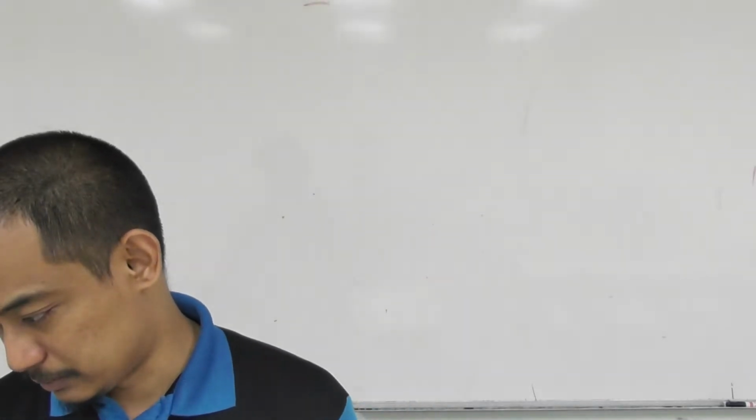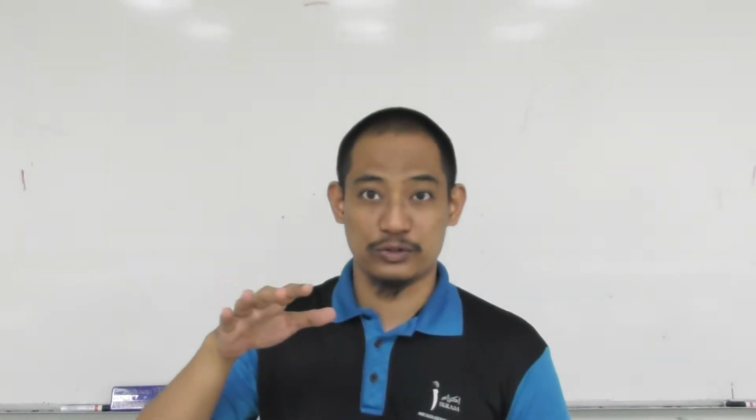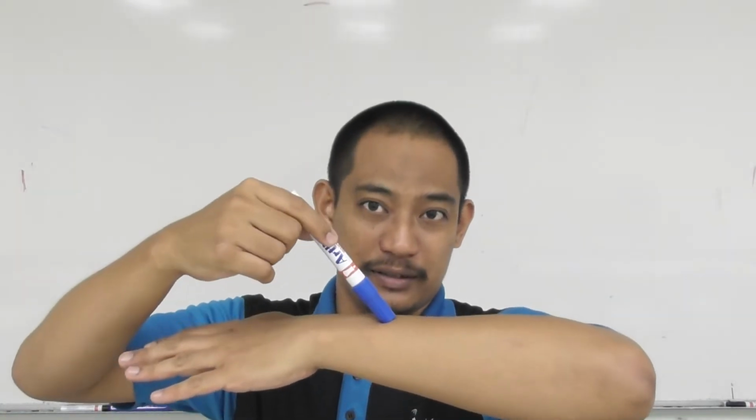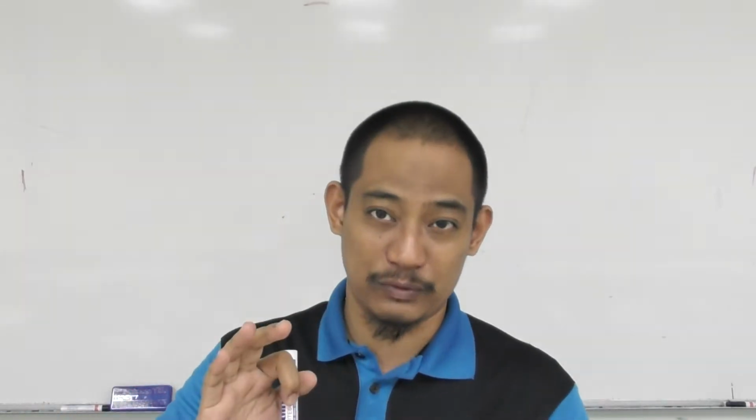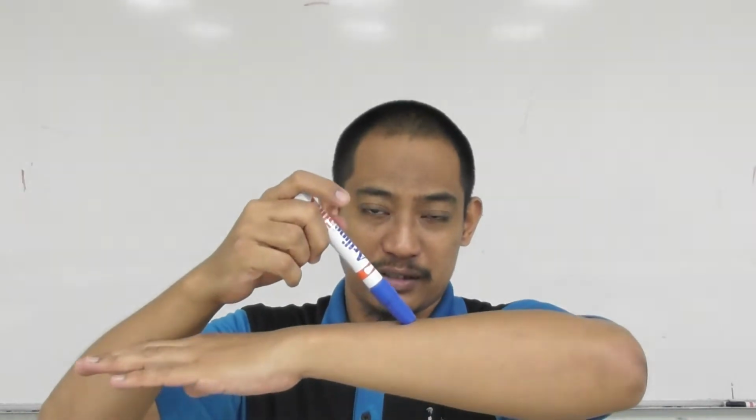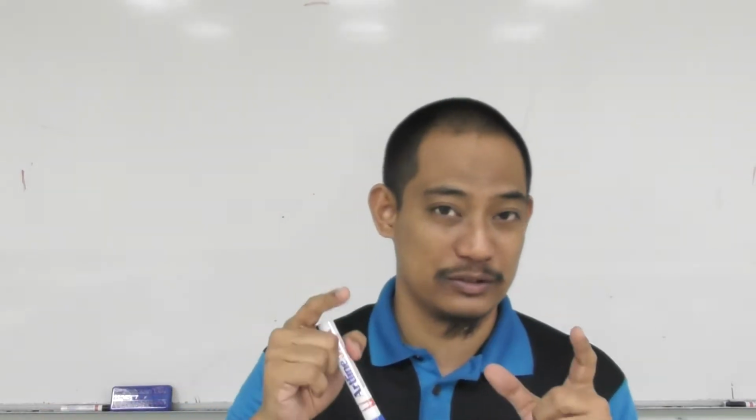But hopefully it's okay, right? Now, there are different type of support that are being shown in the slides, right? So one is just smooth surface support, right? So basically this is if you have a surface and then you have for example the leg of a chair just sitting there, right? So the concept is exactly just what we have discussed in 2D, right? The question that you have to ask is what movement and what rotation does the support restrict, and what movement and rotation does it not restrict, it allows. You can freely move or rotate in that way, right?